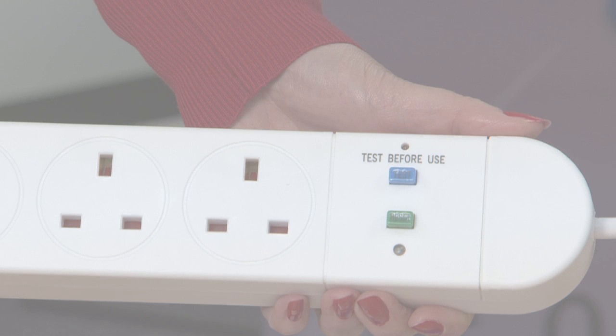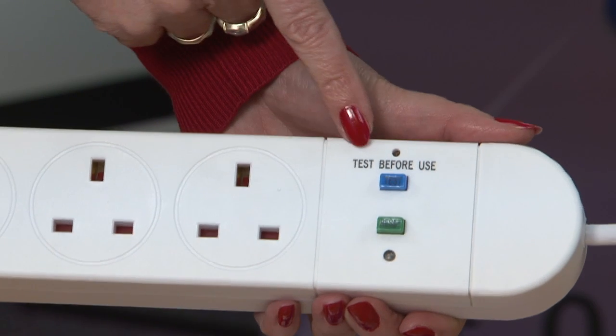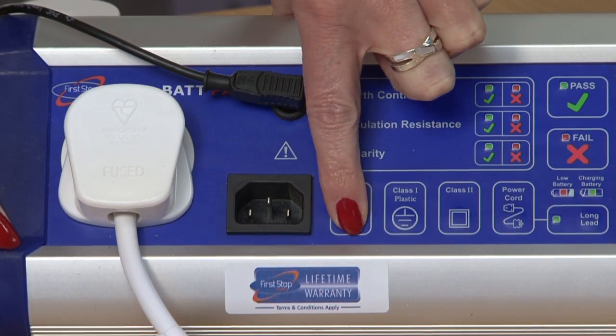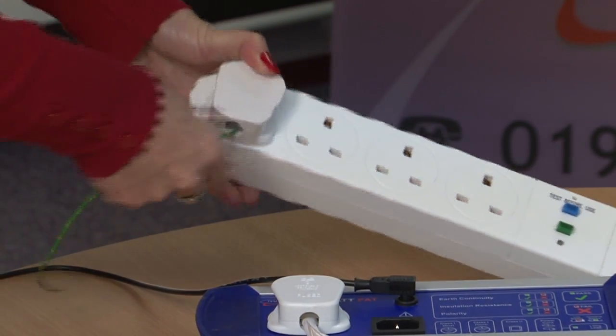Testing extension leads with RCDs. RCD stands for Residual Current Devices. These devices are primarily used to protect you from an electrical shock. Extension leads with RCDs fitted are Class 1 appliances and not extension leads. This is because without mains power, there is no through connection to the mains socket. These need to be tested for earth continuity and insulation resistance. No polarity tests are required here. The easiest way to get an earth connection is by using a plug adapter as shown here.